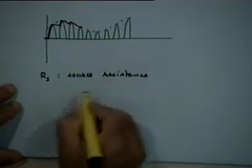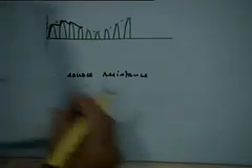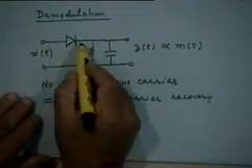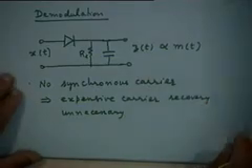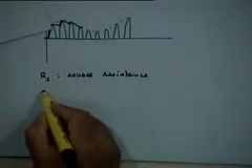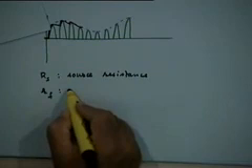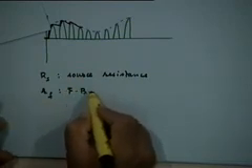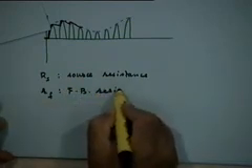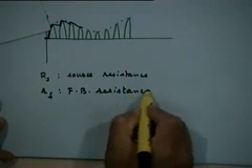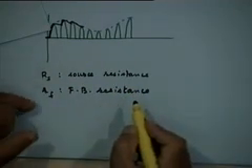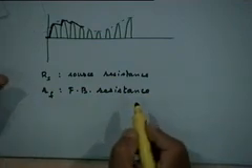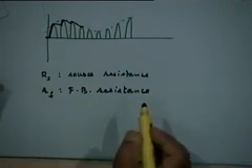Let us say the forward bias. During the forward bias the diode behaves like a simple resistor with a small resistance equal to R sub f. So we can call it the forward bias resistance of the diode, right. Typically both the source resistance, the source impedance, and the forward bias resistance are small values, right.